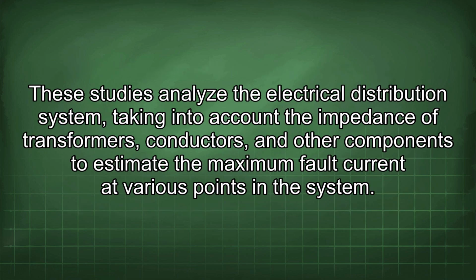These studies analyze the electrical distribution system, taking into account the impedance of transformers, conductors, and other components to estimate the maximum fault current at various points in the system.